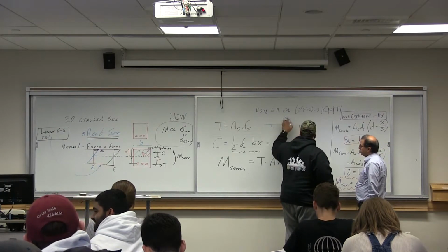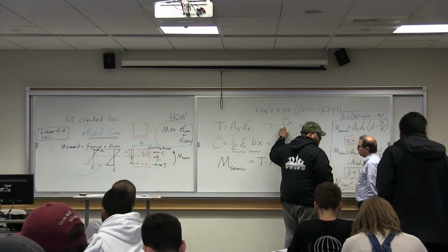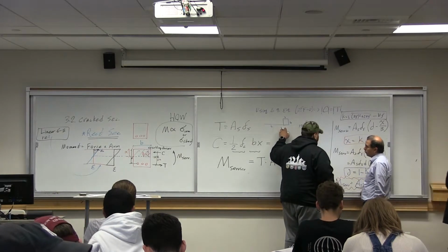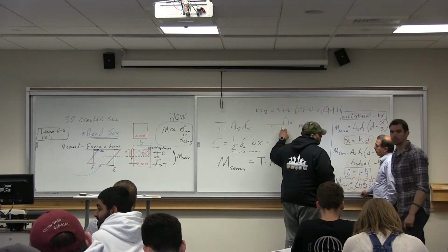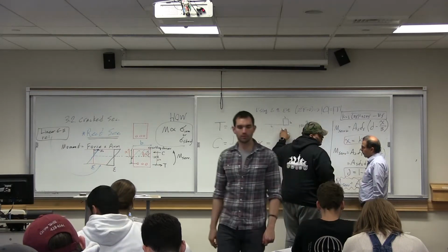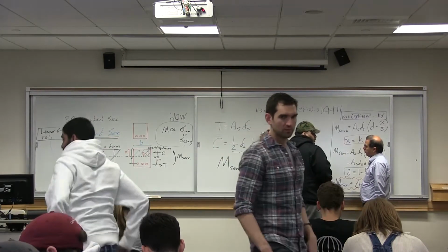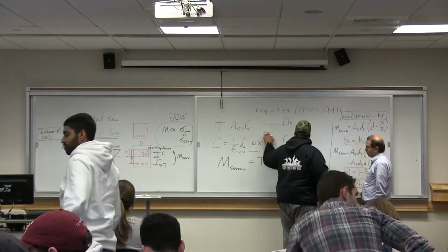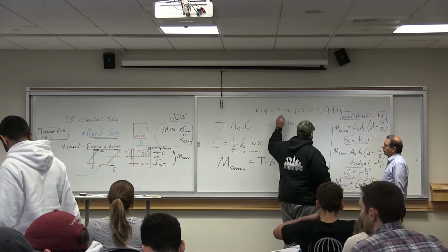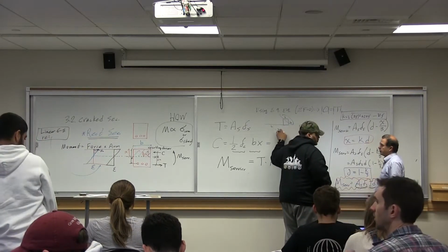Do I just multiply by this volume? And if you multiply by volume, what do you get? I just get pound weight. That's the total weight. Yeah, but I don't get the distributed weight. So if I just times by this area, I'll get pounds per feet, and then that's times 28.